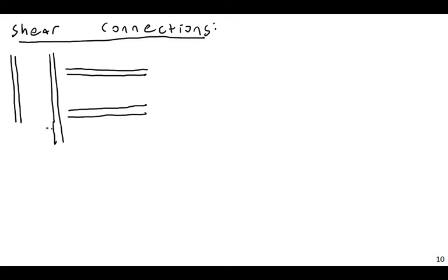And this is going to continue on down here, and this would end here. So if I want to form a shear connection, now we know that the moment capacity of a web is essentially 0. So if I only connect up the web, this connection will not be able to transmit any sort of substantial moment. And that's what I want with a shear or a pin connection.